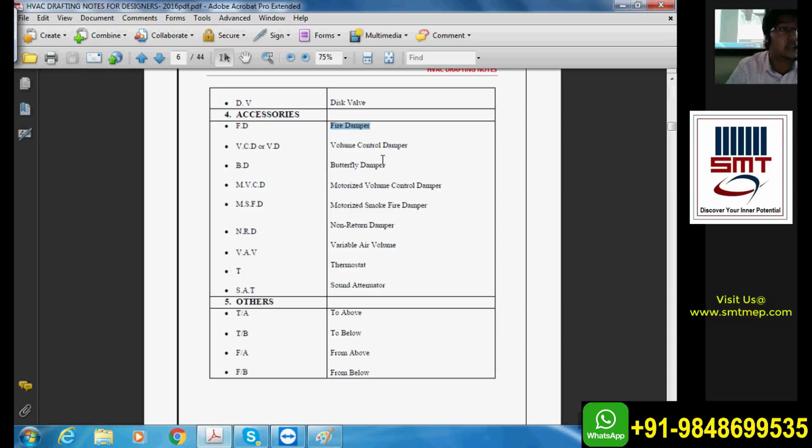Right. अगर main duct के अंदर आग लगती है तो that main duct is only going to be removed. It is going to be again fabricated, have an acoustic insulation applied again. Only one damage is going to be suspended. The branch ducts are going to be dealing good. So for not letting that amount of denser smoke travel and disturb the other necessary margins, the measurements and materials, we need a fire damper in between. Clear? So where to apply the fire damper, how it is going to be created in SLD, in DLD, it's all going to be different.